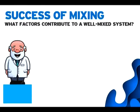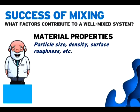The mechanisms previously discussed talk about how mixing happens, but how do we evaluate how successful the mixing process was? Well, the efficiency of mixing is dependent on, first, the materials being mixed. Specifically, the properties such as particle size distribution, density, and surface roughness. Different properties indicate different operating parameters that must be used in order to successfully mix solids. For example, larger particles would logically require less effort to mix due to the decreased variability of the particles.